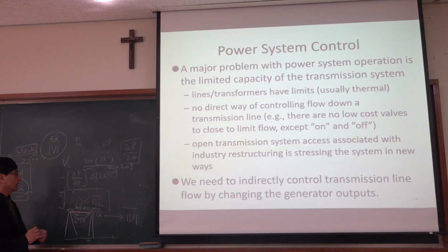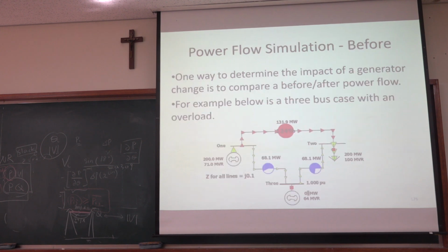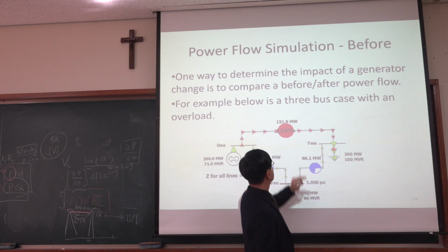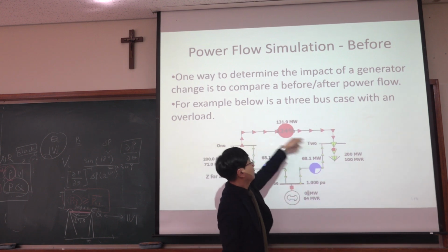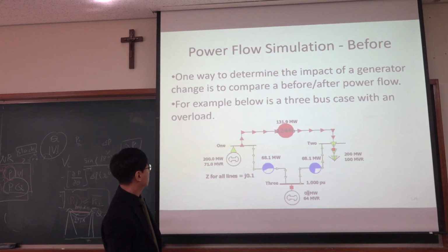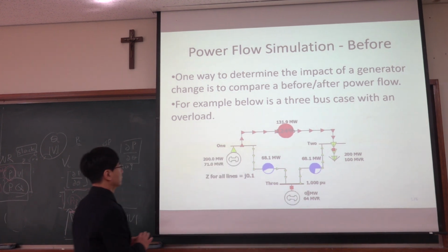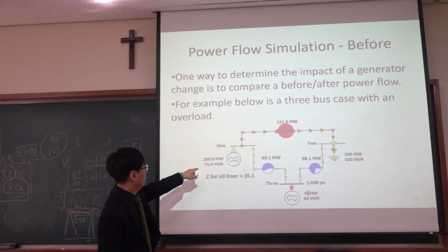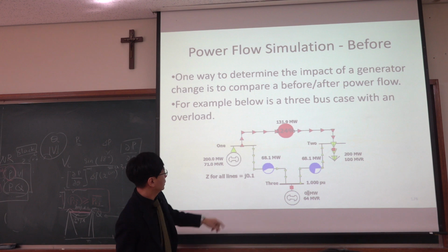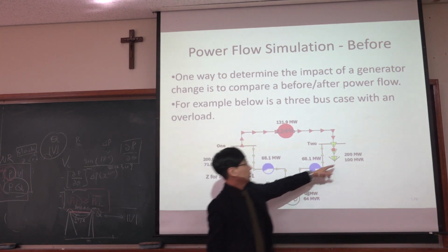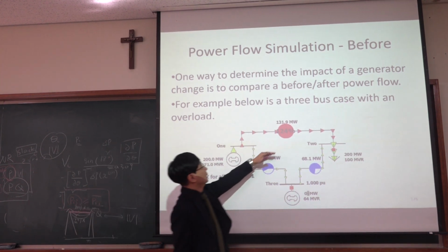And then if we find that some line is congested, actually in your PowerWorld you can see that here, in this 3-bus system: 60%, 73%, but 124%. This is saturated actually. The power flow exceeds the limit of this line capacity. So in this 3-bus example, 1, 2, 3, this is the slack bus, PV bus, and PQ bus. Here all the active power is supplied from this slack bus, and there is no resistance, so no active power losses on this transmission line. So this 200 megawatts is supplied from this slack bus, but that causes this congestion.